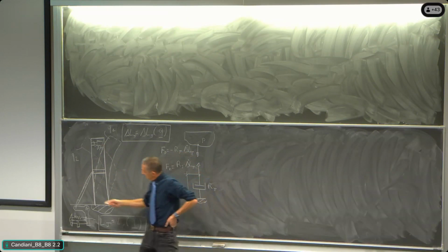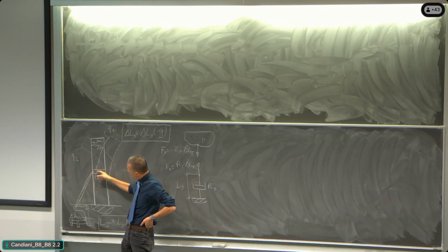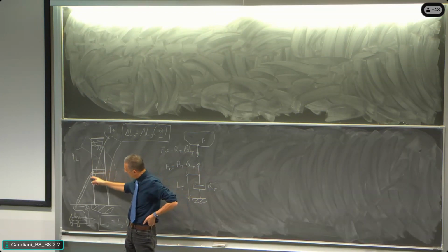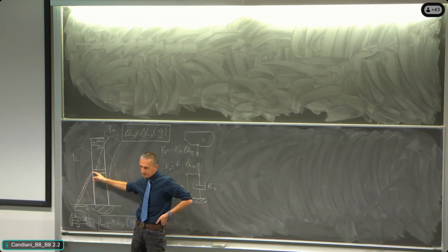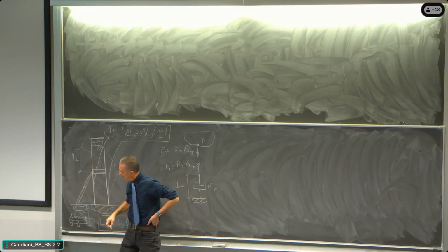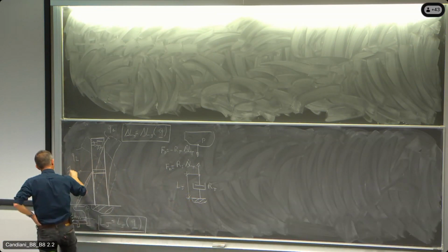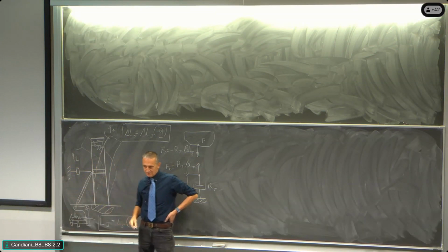All right. And here instead, there is a device that is made like that. It is not very efficient, because you can understand that if there is a movement, yes, I have an elongation of the length that is between this connection and the connection in the tower. But the movement here goes in this direction, all right? And so the damper should be much more effective if it was positioned like that. Okay, but we cannot position a damper in the middle of the sky, and so we cannot do it.